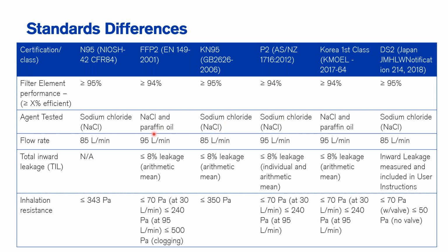What it really means is that oil mist or oil-based particles can affect and degrade the filters over time. So for filters to maintain their maximum efficiency, we need to test with oil-based agents to ensure all different types of particles are being filtered and do not disintegrate the filter capabilities.